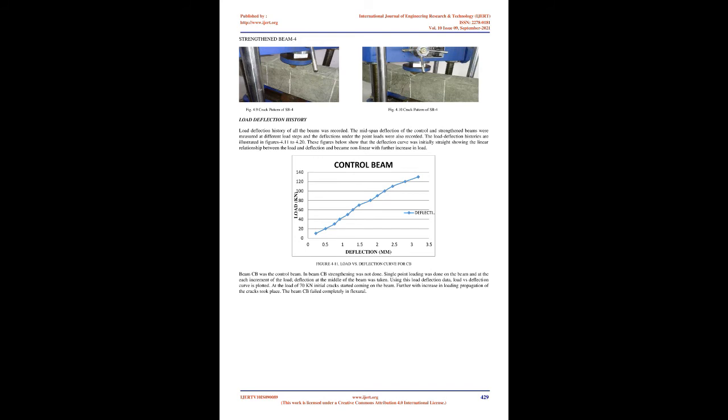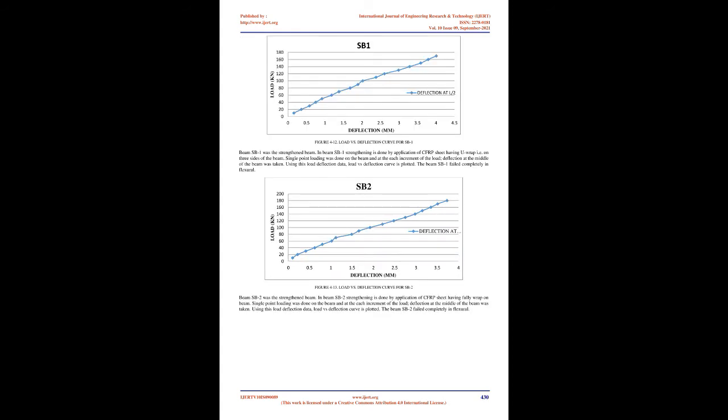During hardening of the epoxy, a constant uniform pressure is applied on the composite fabric surface in order to extrude the excess epoxy resin and to ensure good contact between the epoxy, the concrete and the fabric. This operation is carried out at room temperature. Concrete beams strengthened with carbon fiber fabric are cured for a minimum of 72 hours at room temperature before testing.